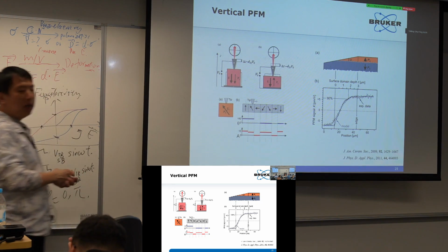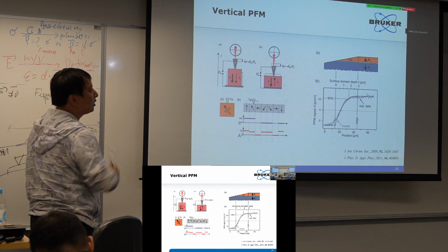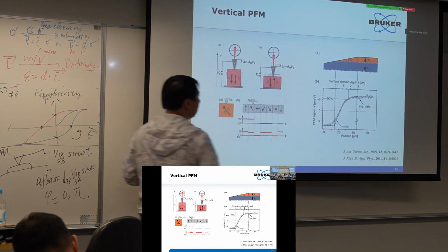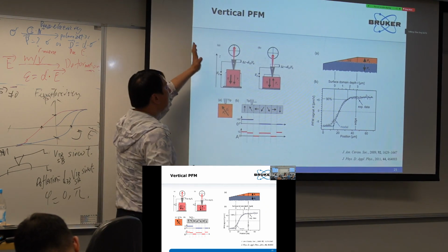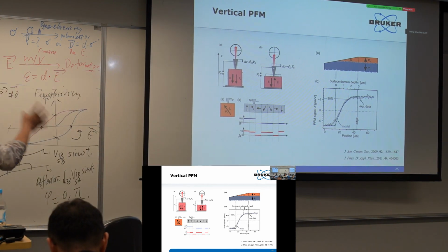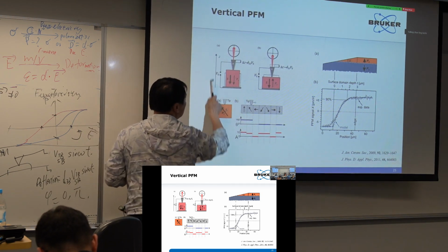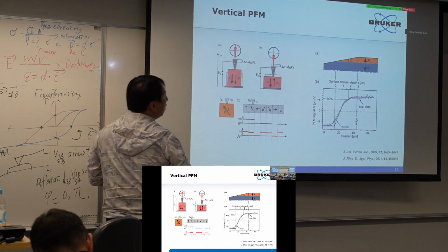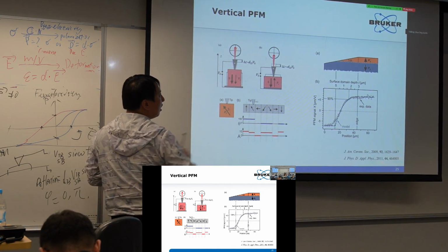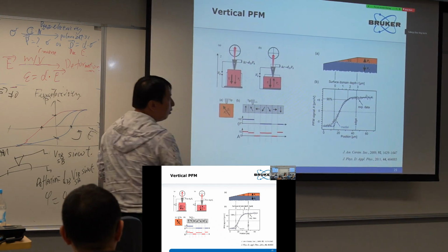But in our actual crystals, it can have various polarization directions. For example, like this one. Since we only study the d33, the d33 has a confined direction: just z-direction field, z-direction deformation. So even if our domains have different directions, we only study their z components.